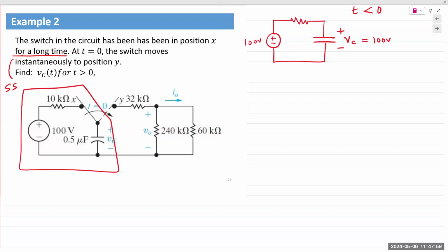A capacitor at full charge behaves like an open circuit. If it's an open circuit, there is no current flowing through the circuit, meaning the resistor voltage is 0. If you apply KVL around the circuit, you obtain 100 volts at the source, 0 volts across the resistor, and 100 volts across the capacitor. Take a pause, think on that.